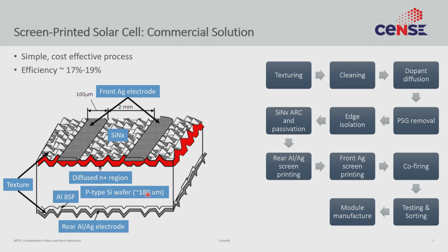Aluminum is a group 3 element, so at least theoretically it should be a p-type dopant in silicon. It's not commonly used because it's a little lossy, but again, silicon solar cells really wanted to optimize cost, and it turns out for various reasons aluminum back surface field is very efficient. So we'll talk a little bit more about it later. For now, let's assume this aluminum back surface field is our p+ layer, so that is common. However, one difference is the p+ layer is continuous, right? It's everywhere, while the p+ layer in the structure that we saw before was confined to some places.